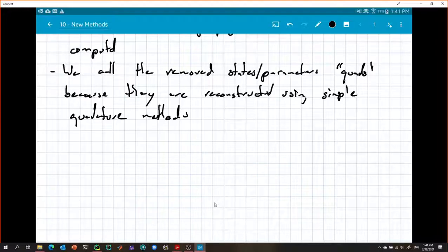If you are solving an aerospace problem on a spherical Earth with latitude and longitude, you could move the Earth underneath the plane, and the control profile you get out would be exactly the same regardless of what latitude and longitude you start at, as long as the relative change in latitude and longitude is the same.